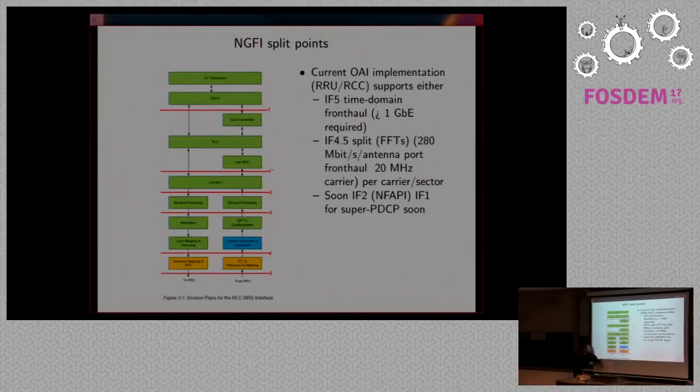From what I'm seeing out there, this interface exists today. 4G uses this. They put a fancy label on it, but this is the CPRI interface today. This one is coming. And it's actually interesting because here, if this is a networked interface, these operations, the Fourier transforms, are running with the radio, and then this is running somewhere else. This one is definitely going to happen. Why? Because here you get a certain amount of compression. I'll show you how that's done later.